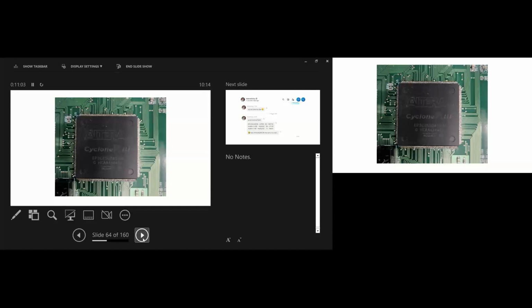It worked. We put it on the board, it's the right size, and we managed to program it, and something came out of it. Just one thing. We had actually ordered a C8N device. If you look closely, this is an I8N device. That's a little bit strange because Altera have never made an I8N version of things. It just makes you wonder, I could have something really valuable, like a misprinted penny black version of an FPGA, or it could be it's dodgy.